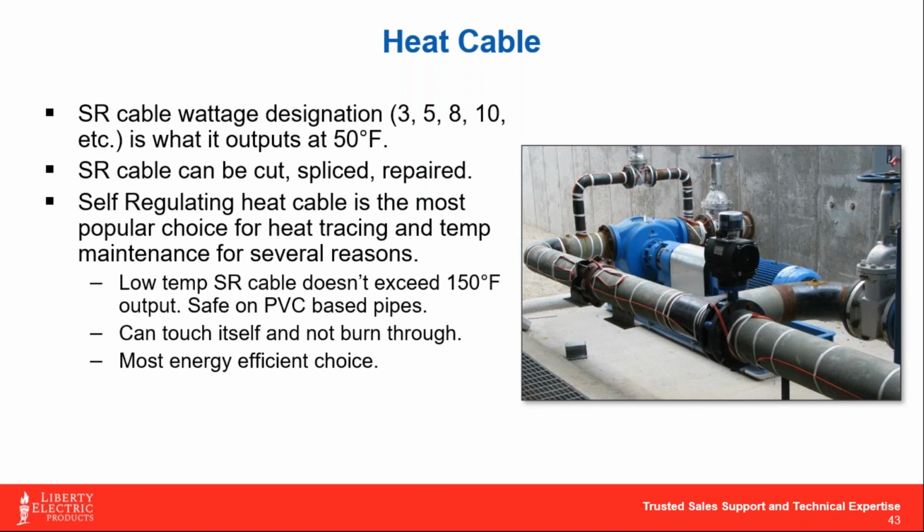So let's dial it in with the correct information up front, and if it requires a special application where we have to use a more robust cable, there's MI cables and constant watt cables that can take higher temperature exposure better than some self-regulating cables can.